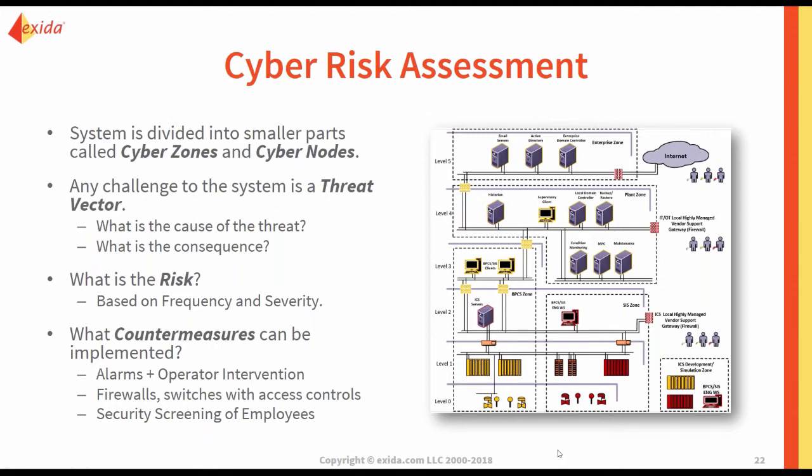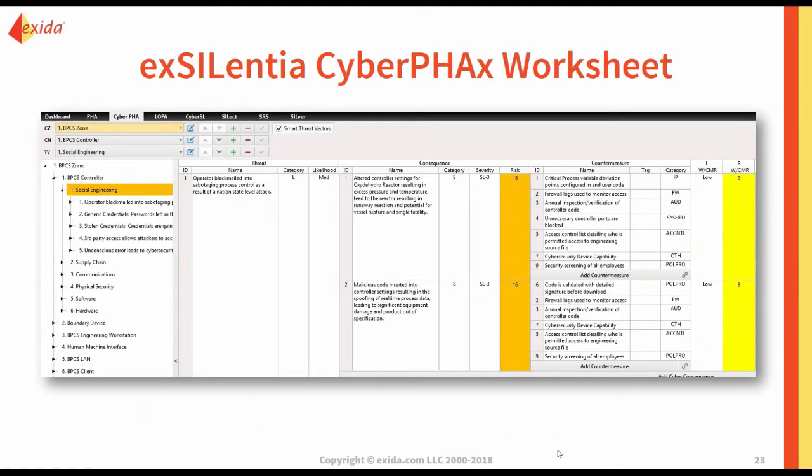And to do this would look much the same. So this is your cyber risk assessment worksheet. This is an exSILentia CyberPHAX. And again, you're breaking down the system into cyber zones, cyber nodes. In this case, the cyber node is the BPCS controller, and then a threat vector. In this case, the threat vector is social engineering.